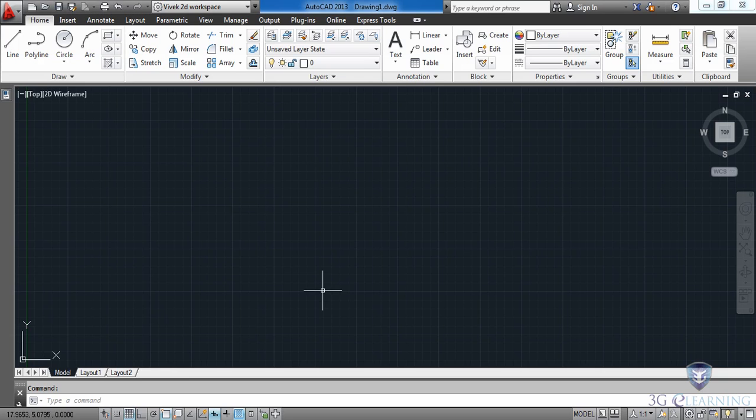In order to use layers to organize a drawing, we need to know how to create layers and manage their settings. In this lesson, we're going to explore the Layer Properties Manager, the one-stop shop for all your layer needs. As you can see, I've just launched AutoCAD and I'm sitting in the currently unsaved drawing 1.dwg file. Since this drawing is based on the default template, it's virtually empty. If I open the layer control, you can see we only have one layer, layer 0.